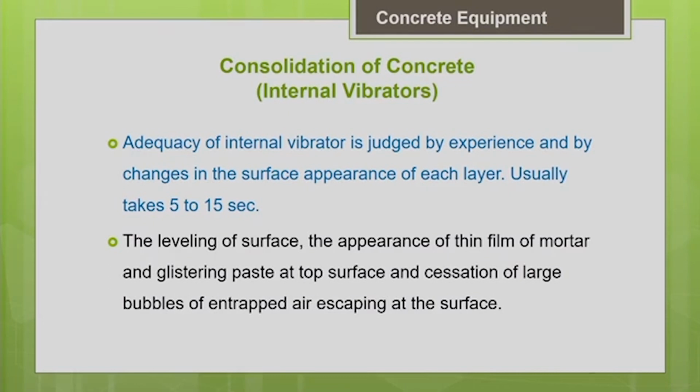Generally, based upon experience, what the worker will do is look at the concrete surface itself and make a guess whether the consolidation is done or not. If he is an experienced person, he can make that guess. Your surface will appear very level, and the air bubbles which come to the surface will stop coming. That is an indication that consolidation is done.